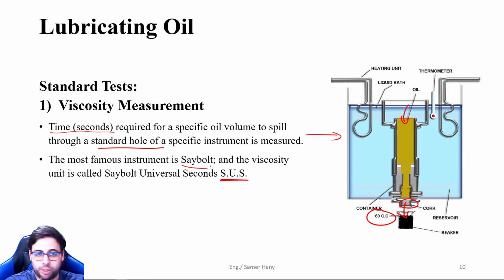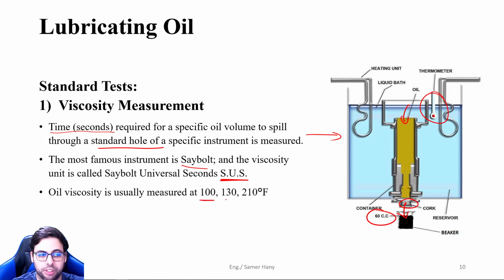Okay, so as we discussed, if 2 or 3 different people did this test, each one will get a different result for the same oil based on the temperature they worked at. So this test is conducted at 100 degrees Fahrenheit, 130 and 210. Then we go and see how our oil viscosity is performing according to the standards.